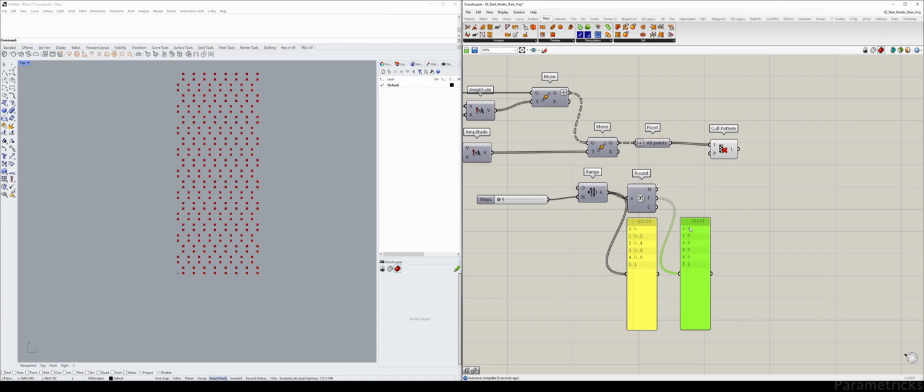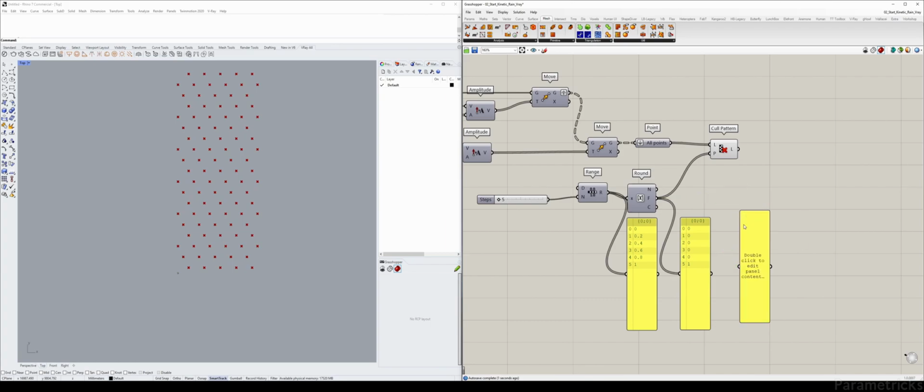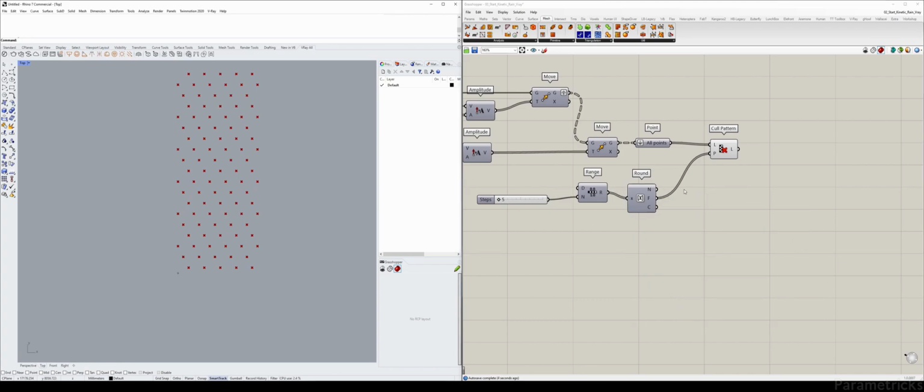And what that will translate to, if I just quickly put a Boolean, I hope it works like this, you'll see that it's false, false, false, and then true. So we can actually use this directly, or we can use this. Grasshopper translates that automatically for you, so you don't really need this Boolean toggle. So I'm going to get rid of that. So now you can see we have 101 points with a certain pattern.